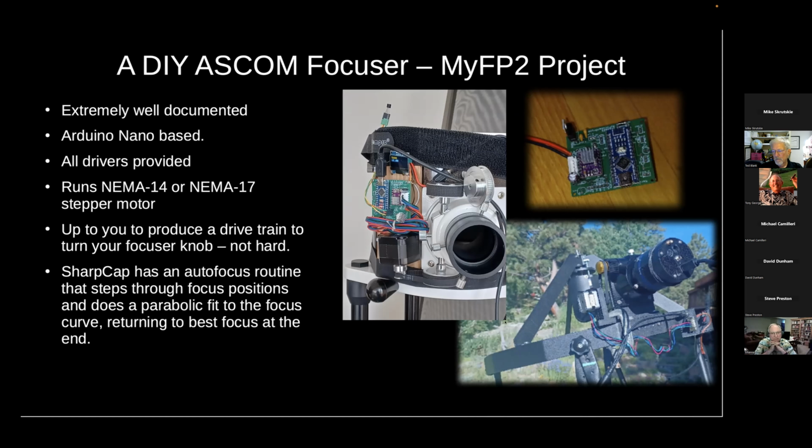So on the right, you see my Skywatcher interface where I put all this stuff on a piece of oak and I banded it. I just Velcro stretch banded it to the telescope. And there is a timing belt matched to a gear on the stepper motor. And I actually on the Skywatcher just let this belt grab onto the rubber of the focus knob, and there's no backlash in this system. It works very nice. This is the top of my Hubble Optics telescope.